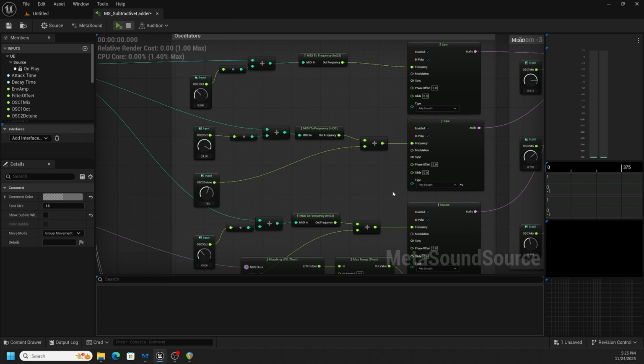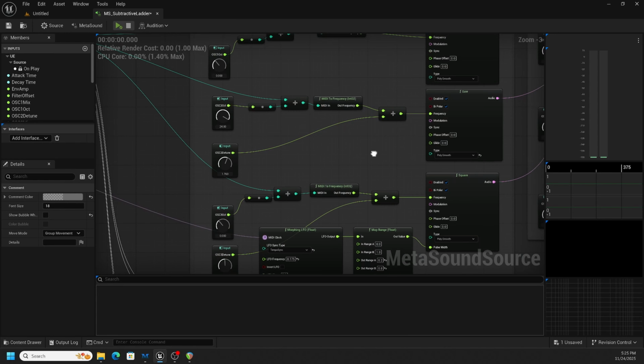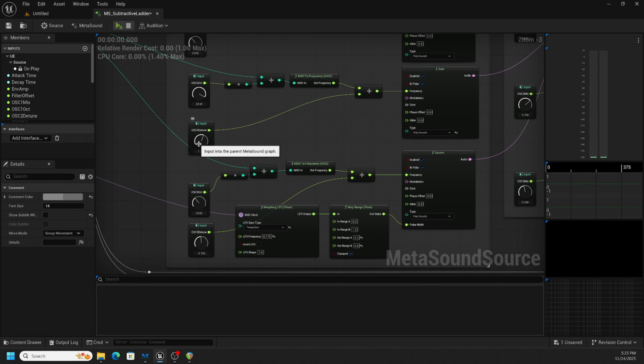Another aspect that's really important is being able to detune an oscillator. So on oscillator 2 and 3, I have the ability to detune them or put them slightly out of tune. This is especially important in digital formats, where oscillators can be perfectly in tune. That was much more difficult to achieve in analog oscillators, VCOs that were controlled by voltages. It was difficult to get them perfectly in tune with each other and to track perfectly over the range of a keyboard. But in the digital system, they do that so perfectly that it's a problem.